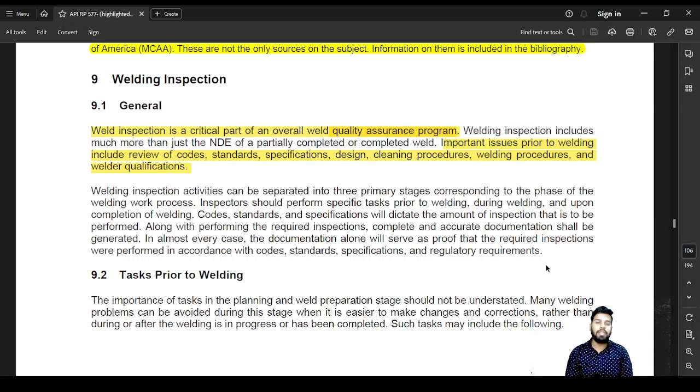It is basically common sense when you think about it, but obviously we already understand that the weld is to be inspected 3 times. It has to be tested before welding to identify if the base metals are correct, if the edge preparation is done as per the requirement, if the electrodes are treated correctly, if the equipment is calibrated. All of those things would be done before welding. During welding we'll check welding parameters such as if the passes are done as per the requirement, what is the travel speed, what are the electrical characteristics, what is the heat requirement, what is the voltage requirement, what is the current requirement. All of these would be during welding. And after welding, obviously we'll do visual inspection and various kinds of non-destructive examination to identify defects.